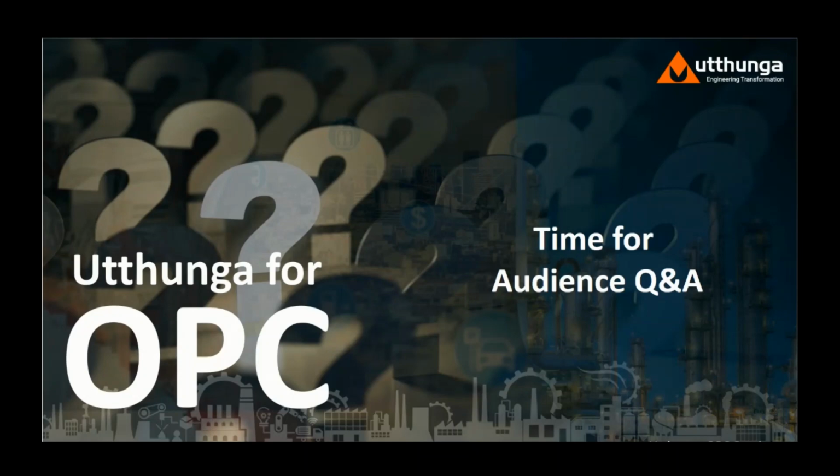So what you are really asking is, do you use MQTT based on your own formatting, your own message encoding format, against using OPC UA's prescribed JSON format, but again with MQTT itself. So MQTT is common in both. The difference is the encoding which you will be using.